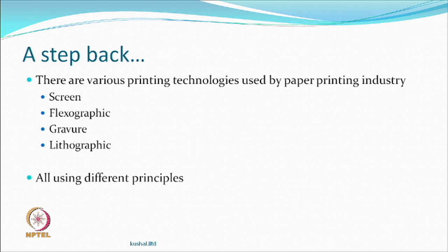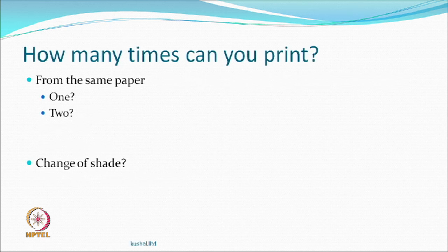And of course, their principles are very different, and I am sure you would have appreciated the difference in the principles. Some people can ask this question: if you have the paper and you have done the transfer, how many times can you use the same paper? We said the cost of the paper is high. So, theoretically, obviously one time you can use it, and if you do a good job, which you should, a large amount of dye would get transferred, but it is never 100% transfer.